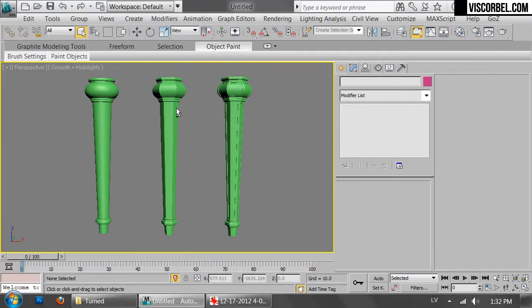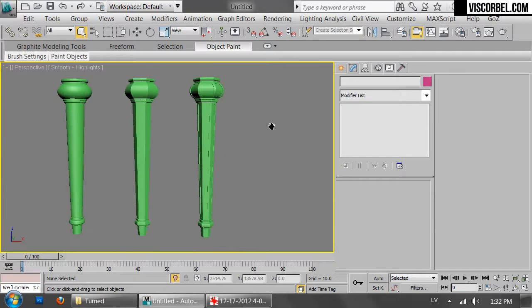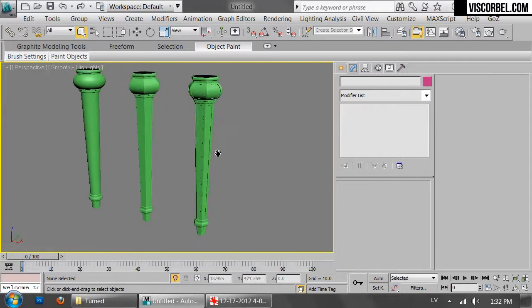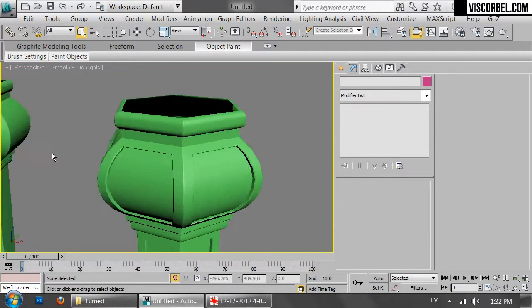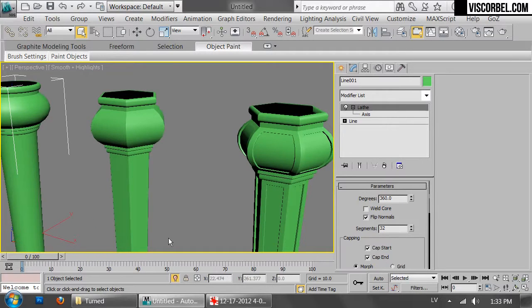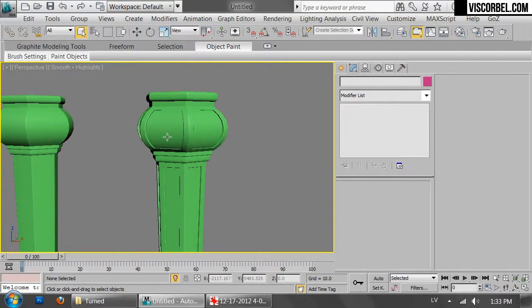And that's a simple but useful technique to use on segmented turnings that you need to adjust multiple parts of simultaneously. It gets really helpful when you have more pieces than 6. For example, you have almost round with 60 pieces and you need to adjust just one slice or 2 slices of that, and you can do that. You just have to calculate how many copies to use with the array tool.